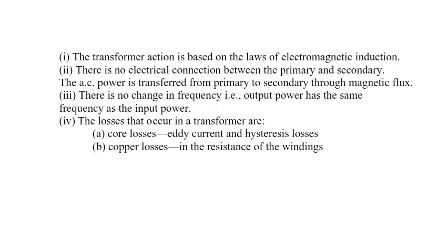Transformer action is based on the laws of electromagnetic induction. There is no electrical connection between primary and secondary; they don't even touch each other. Then how is power transferred? This is through magnetic flux, the change in magnetic flux. We are using this principle. There is no change in frequency. The output power has the same frequency as the input.